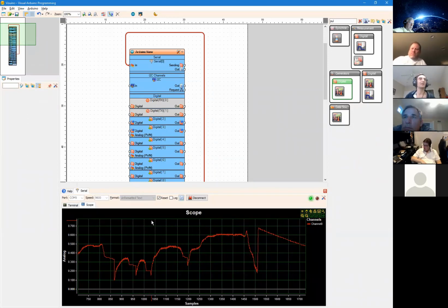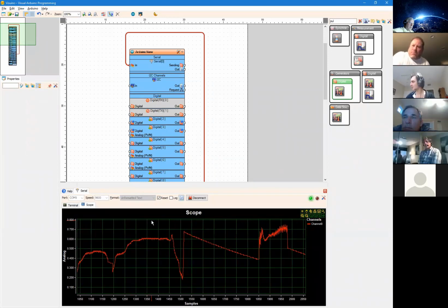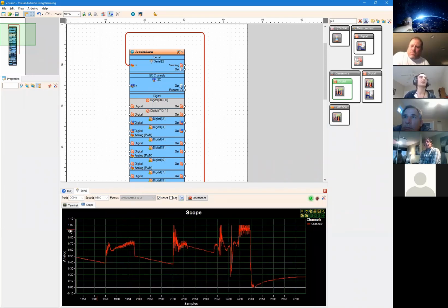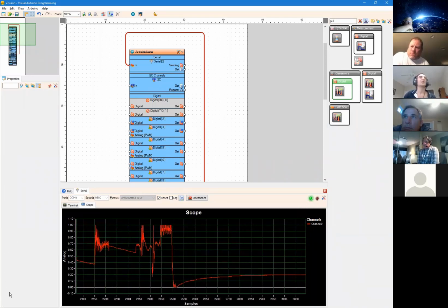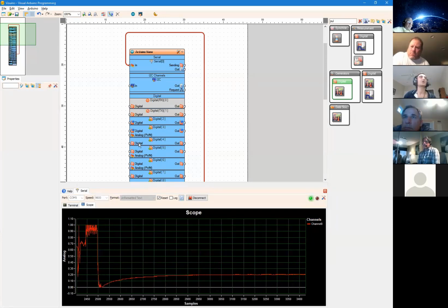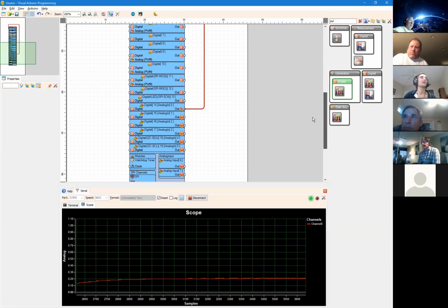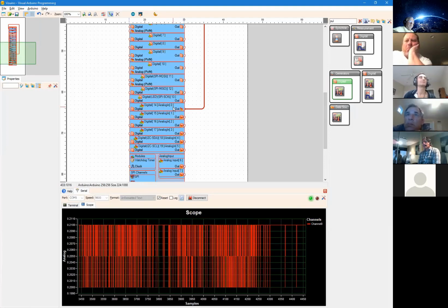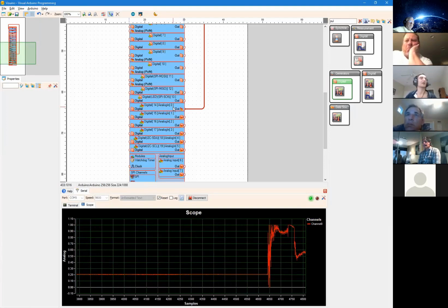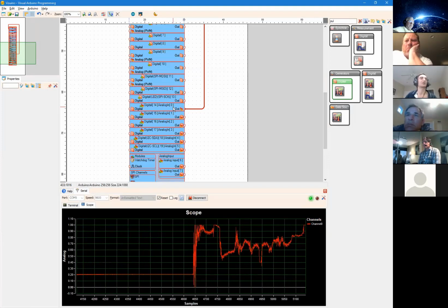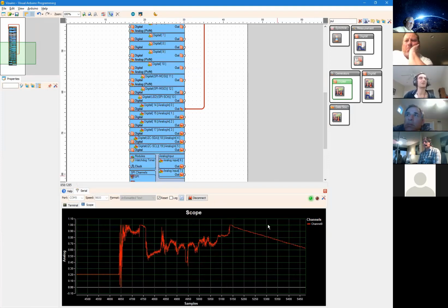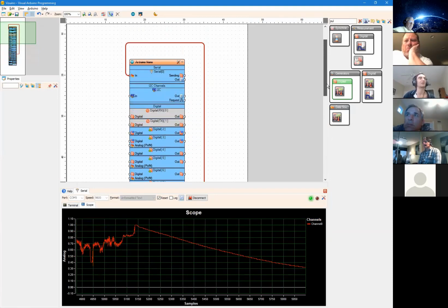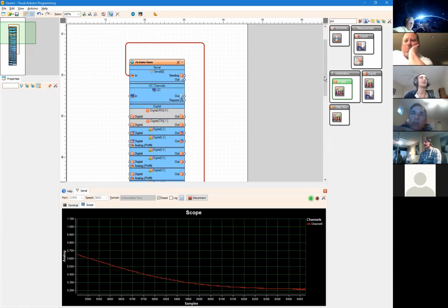So are you just touching the analog input? I am. What are you sensing? Is it a temperature sensor? Right at the moment, I'm sensing, and I'll show you again, analog input 0. You see that? Uh-huh. And again, as soon as I touch it, I'm going to introduce some noise because I don't have a physical sensor. And yeah, it has some capacitance, so it's dropping now from the capacitance when I release the pin.